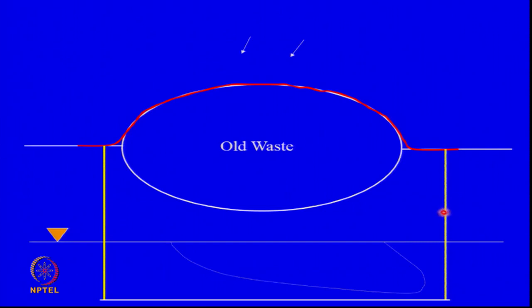So the tendency to make vertical walls very deep is always there, but you may not find an impervious strata at the bottom. It is possible to make an impervious stratum, an impervious barrier at the bottom of a plume. It's exorbitantly expensive. It is not done. But technology is there if you want to make it, including going and tunneling underneath this and making a barrier.